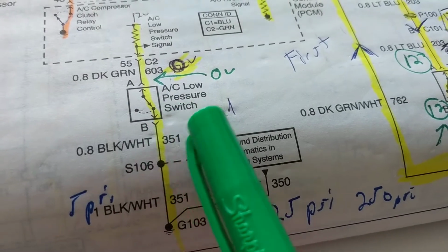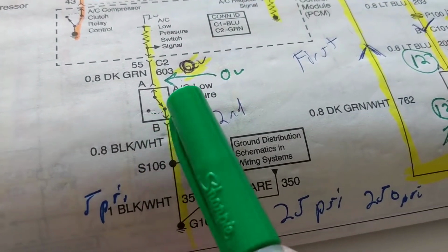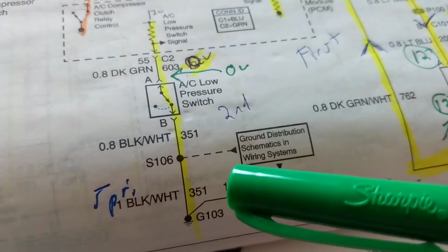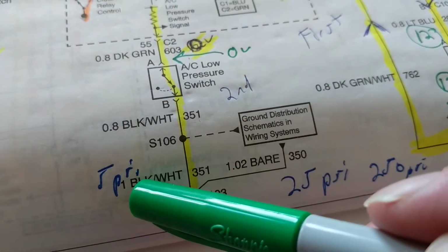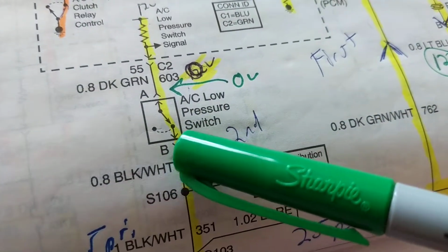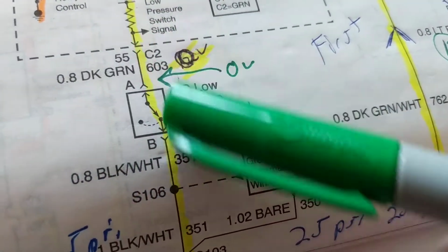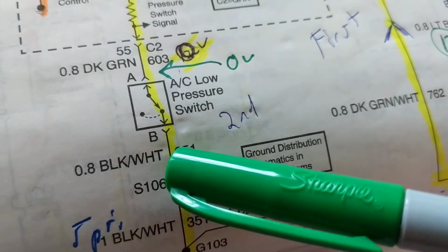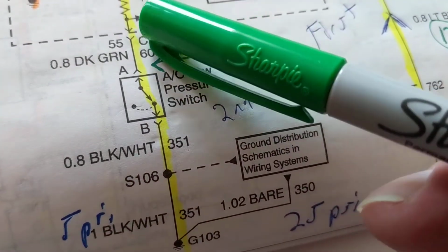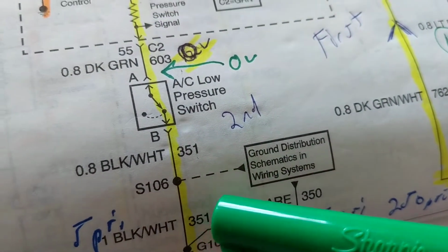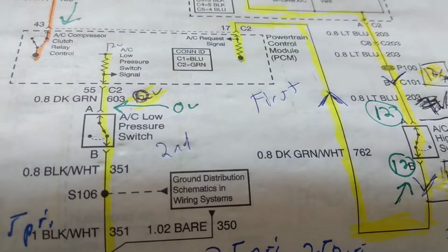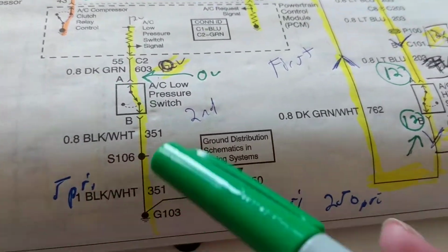Well, let's say the AC low pressure switch is open, meaning instead of here in the yellow, it'll be here, because it is 5 psi and it's very low and it's supposed to be open. By putting a short across it, now you're actually jumping something that's supposed to be open because the pressure is low. That's not good. If you don't see the damage now, you'll see the damage later on with leaks and bad components. That's why I don't recommend to do so.